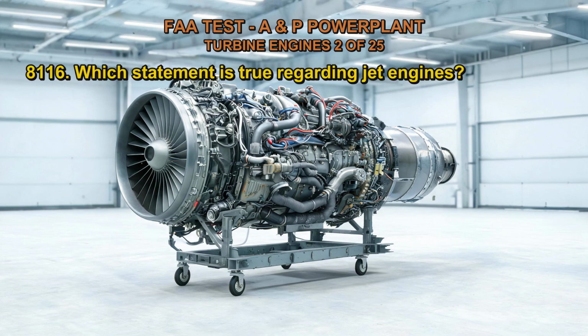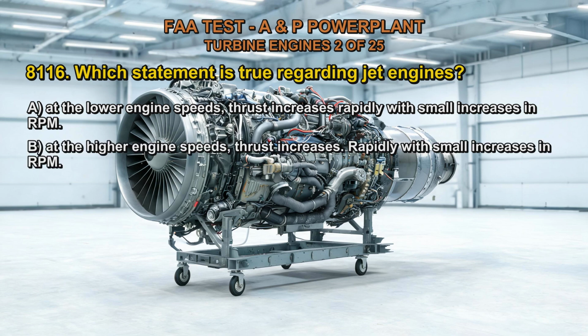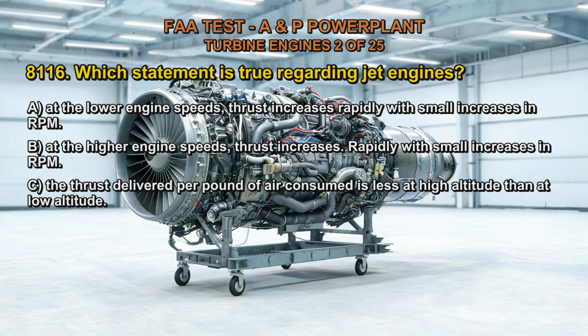Q8116. Which statement is true regarding jet engines? A. At the lower engine speeds, thrust increases rapidly with small increases in RPM. B. At the higher engine speeds, thrust increases rapidly with small increases in RPM. C. The thrust delivered per pound of air consumed is less at high altitude than at low altitude. The correct answer is B.